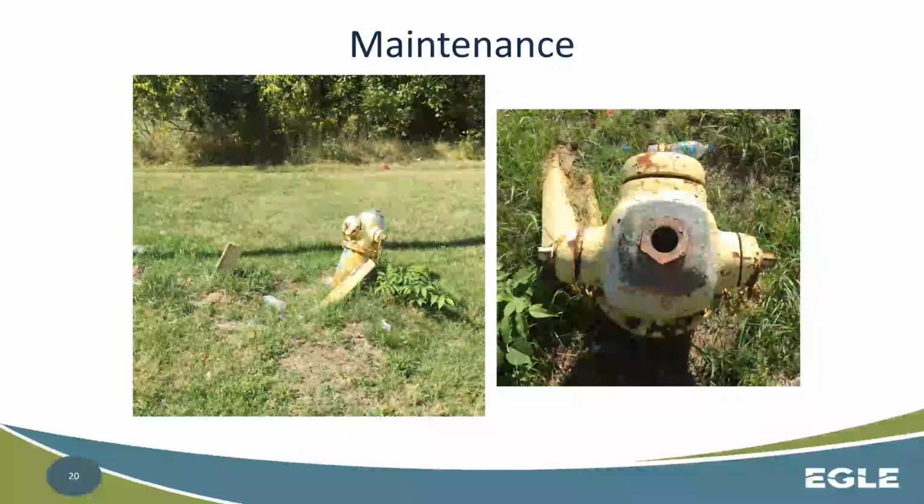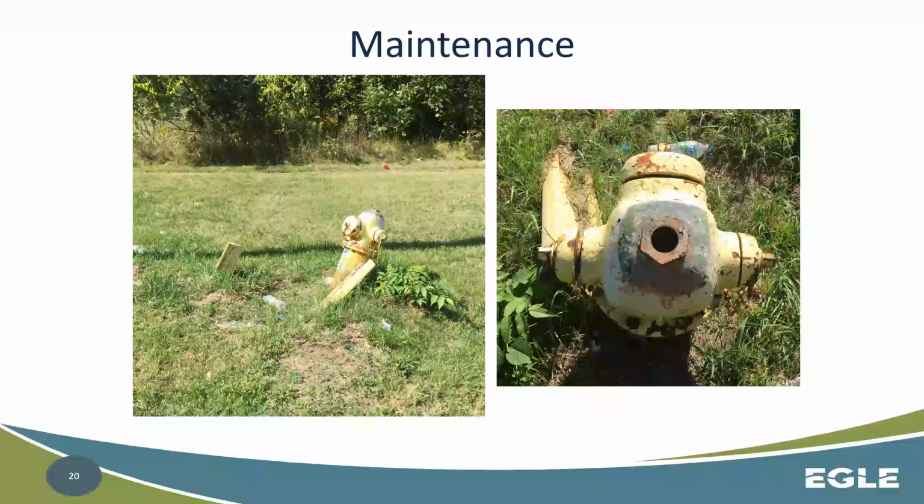In this situation, this is just clearly an inactive hydrant. This is one that should just be removed from service. We should be trying to take a little bit of pride in our water system and not allowing things to get to this point. And if we're not going to have a hydrant that is serviceable or usable, we should be removing it, making sure that we have a proper cap and a proper backstop to that cap on the line and getting it out, or just replacing it altogether with a new one if there should be one there.